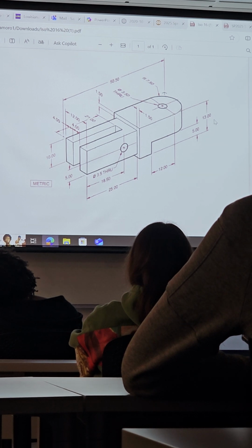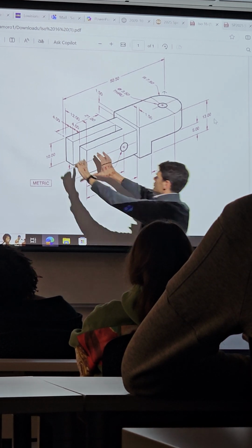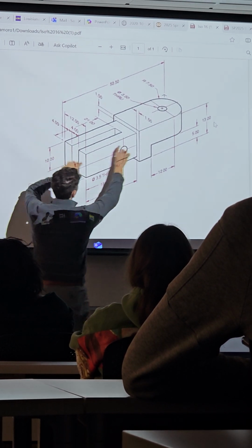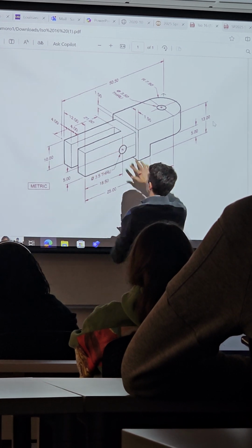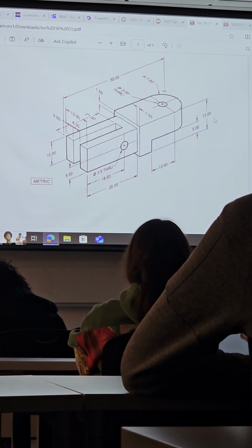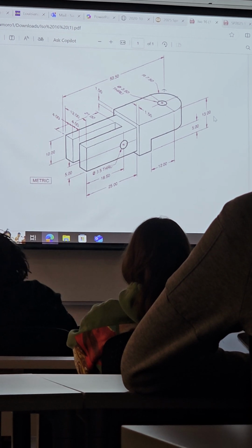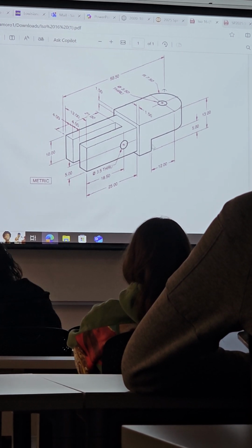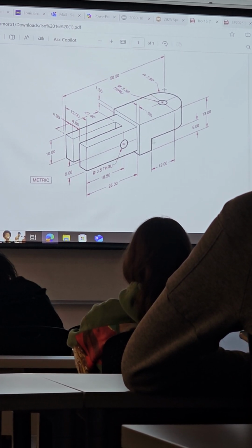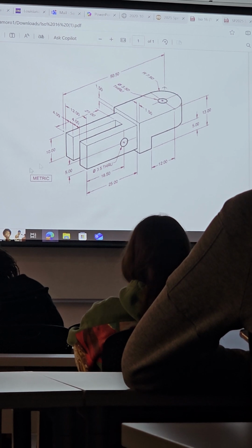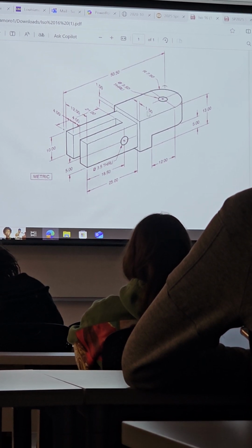So I'm going to focus on drawing these three rectangles, 1, 2, and 3, and then I'll come back and catch these hidden lines. Oh, I also need a hidden line for this invisible edge back here that's not visible when you're looking from this